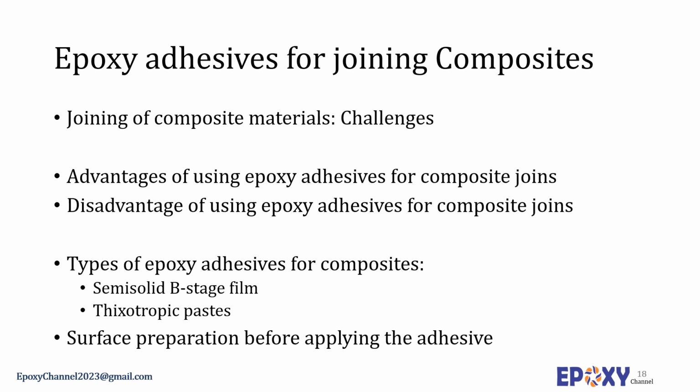The film adhesives are cast or extruded onto carrier fabrics or films and partially cured to a semi-solid. They can easily be handled, cut, and applied to the joining area. There is no need for mixing, metering, or dispensing of liquid components. These adhesive systems are activated by heat and pressure. The semi-solid B-stage film liquefies briefly on application of heat and then cures to an insoluble state. Epoxy polyimides, epoxy nylons, epoxy phenolic, and nitrile phenolic adhesives are available as B-stage film.